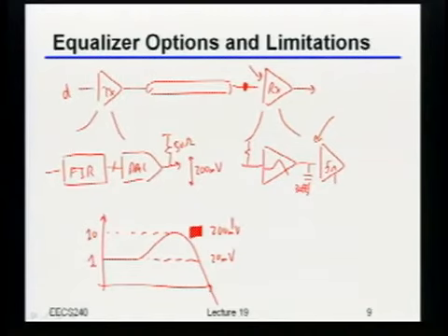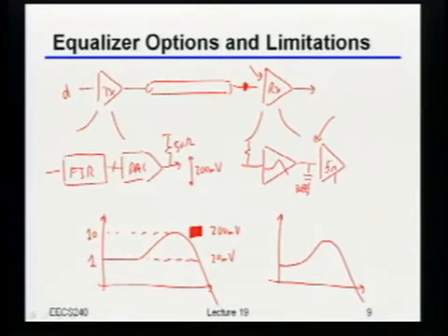It's just a fancy way of saying that if you have to go through a low-pass filter, and you have to equalize the thing, you're going to get more noise than you would have if you didn't have to do that. Now again, I'm doing this on the transmitter because it's easier to see why this is happening there. But if you don't believe me, on the receiver it's a similar idea. When I implement a function that looks like this, as we'll see in a second, usually the way you have to do that is if you had a certain peak gain, you're just going to have to throw away that gain at DC.